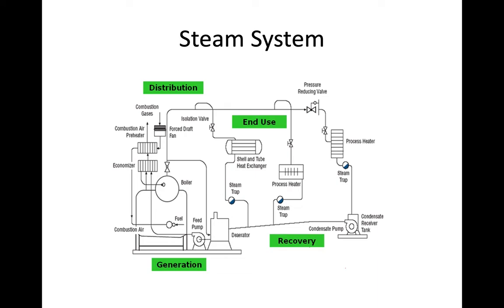We prevent them from entering the boiler, because these minerals will not evaporate in the boiler, and as a result they become contaminants that can plug or clog the piping system.